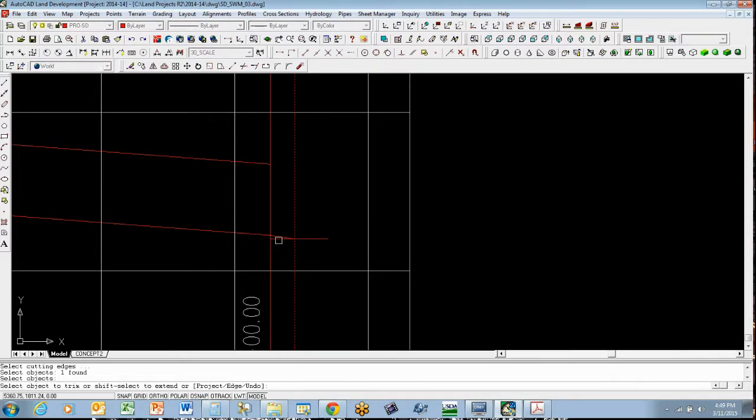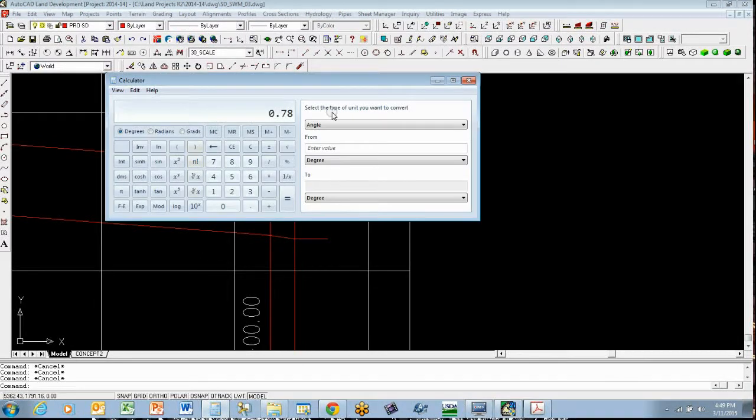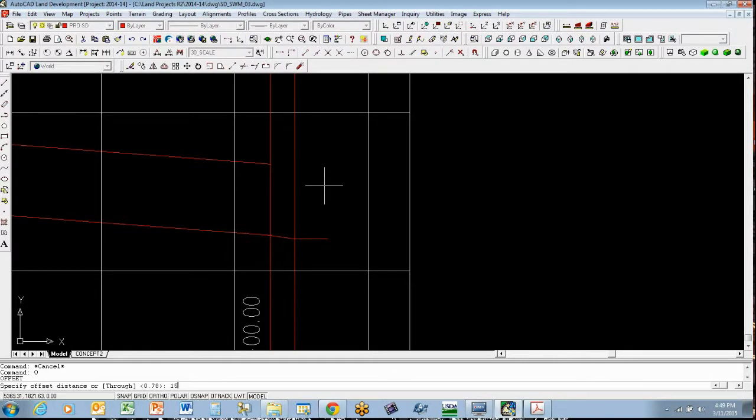Okay. And this pipe is actually a 30-inch RCP that discharges out of it. So 30-inch RCP. And we just need to show it. 30 inches is the same thing as 2.5 feet, so we go 2.5 times 6, 15 offset units. Offset is 15. And that's the top of our pipe. Okay.